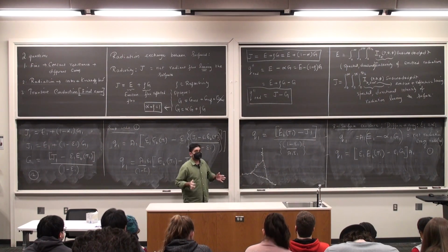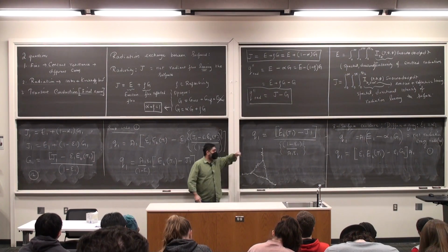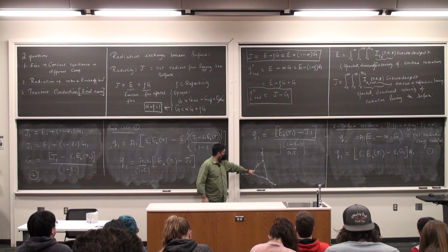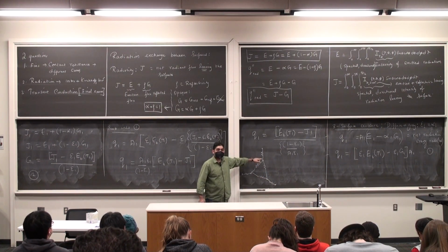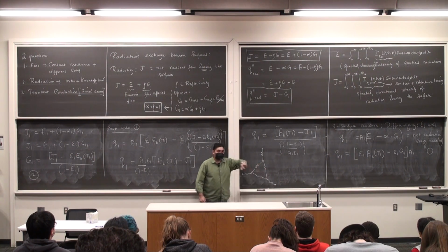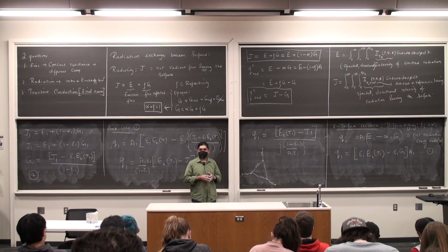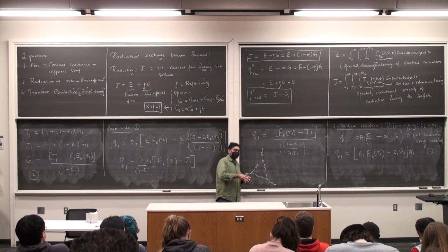Where all of the foundational nodes will be the emissive power of an ideal body at temperatures T1, T2 and T3. All of these inner nodes will be J1, J2 and J3. The inner resistances will be coming from the fractions. The outer resistances will be coming from the surface areas. And this is what we are going to do in the next class.